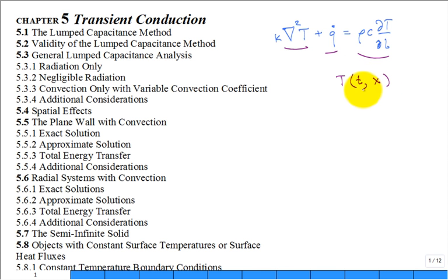Well, when we first start into it, it seems very funny that we're going to have transient conduction, but we're going to neglect the conduction. And it'll be a lump capacitance. And so the boundary condition is convection, and there's no real conduction resistance. It's neglected within the system. So that's the first two parts.